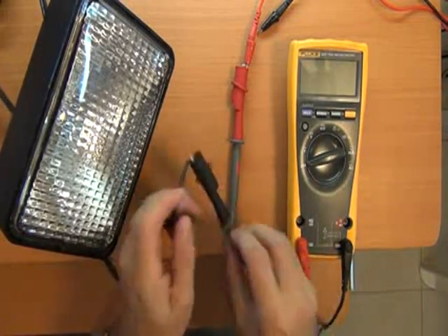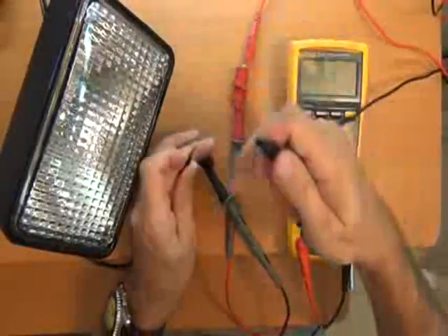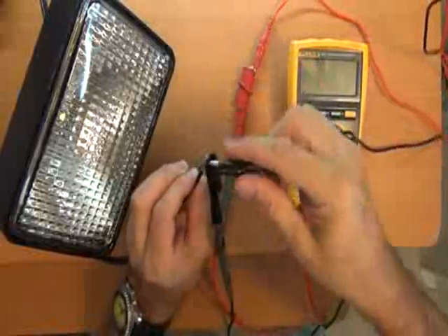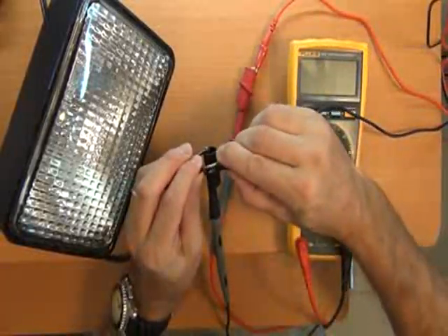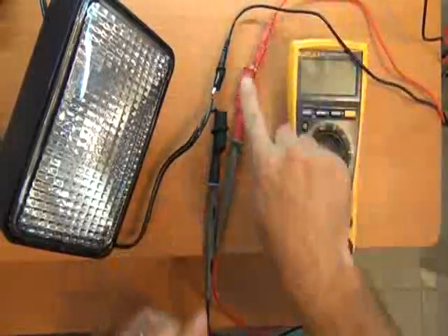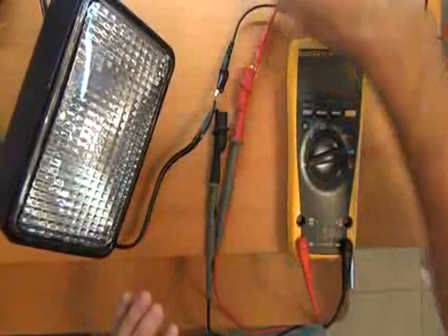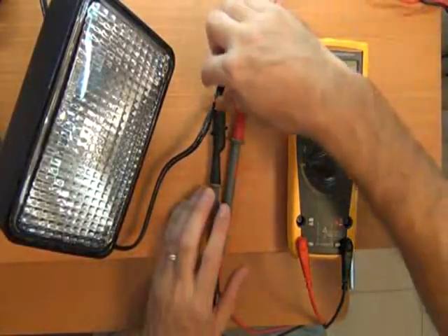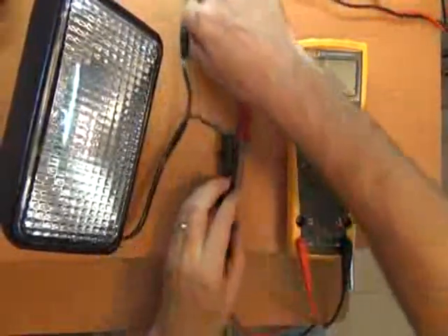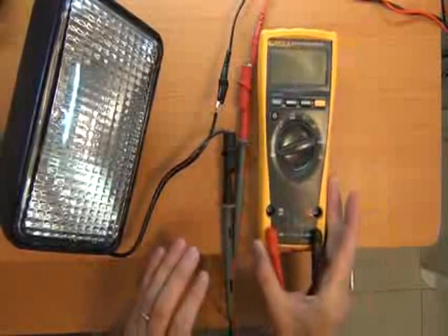So that's clipped on there like that, and then I can directly take the negative, in essence this side, this is the negative side of the power supply. It gets connected like that, and what we want to make sure is that the wires are all apart and we're not going to get a short. So I've got them laid out like this. Let's make sure they're not going to touch. I'll even pull these wires apart to make sure, so that looks safe.